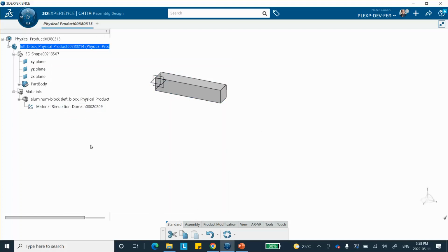In all likelihood, that red discrepancy between the stresses on the two sides has to do with the Poisson ratio. So if the Poisson ratios of the two materials are made the same, probably you won't get that sharp red interface. Okay, that takes care of this.